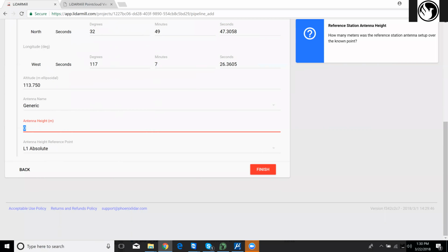Except for fixed tripods, this is where I see folks mess up the most. Either they forget to measure the HI or transpose the numbers, and when they get to the processing side, your data is pretty much useless if your HI is wrong, and there's no way to step back and prove what's right once you've broken down your base station.